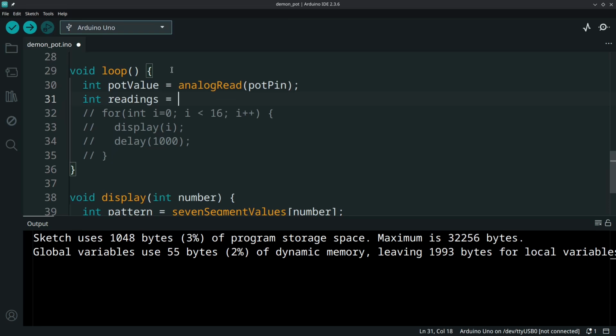You get our readings from map, a function we explained in the previous video. Also explain this: that's the port value from our ADC. The ADC is 10 bits, so we move from 0 to 2 raised to power 10 minus 1, that is 1024 minus 1, 1023. So it covers from 0 to that.